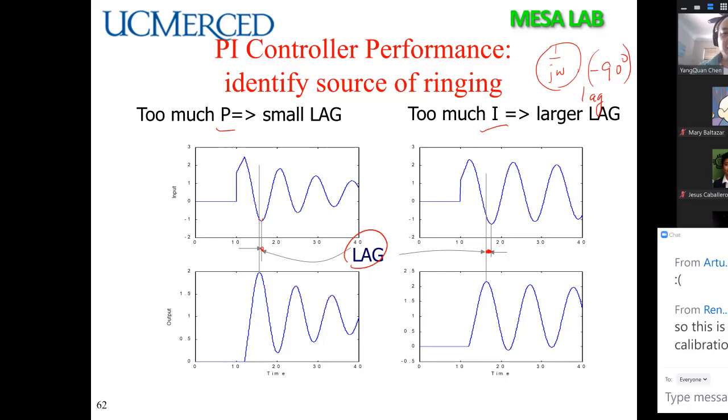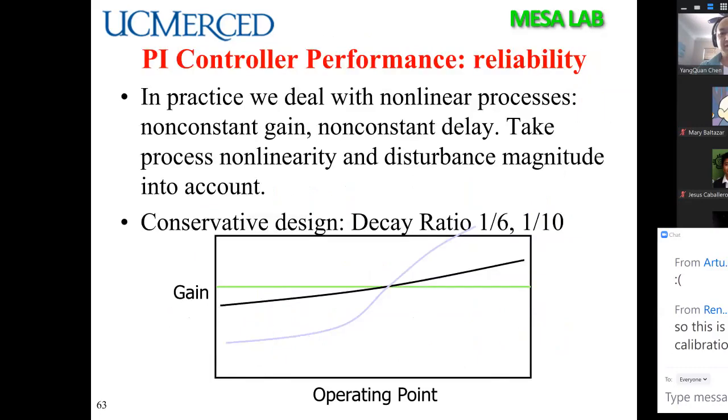So in an industry setting, if you find out the system is ringing, it's chasing each other, it's bad. Your supervisor is scared. So just record the curve and show him, hey, look, we can reduce the integration gain, okay, and perhaps we should reduce the overall gain. So these are some ideas you can use in industry. So that's talking about oscillation.